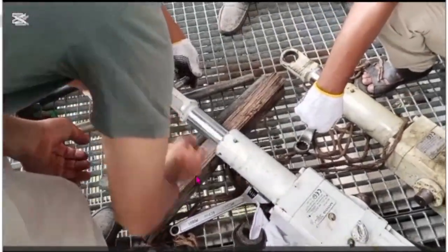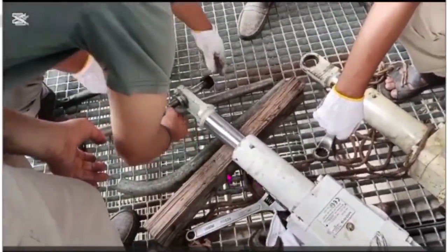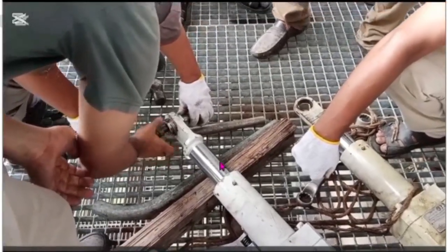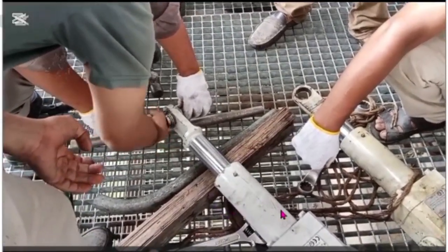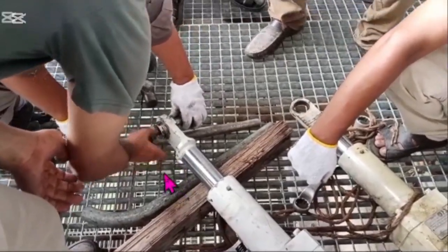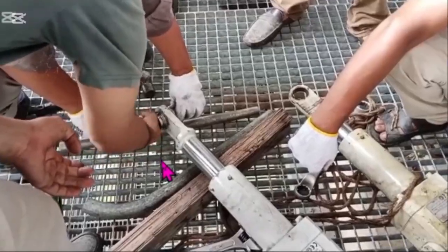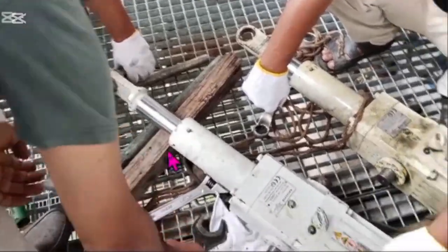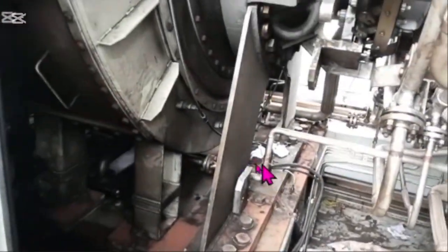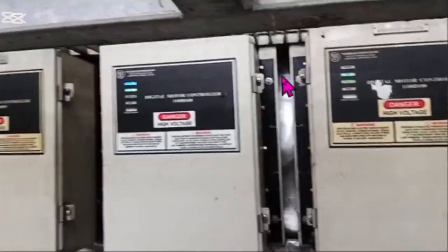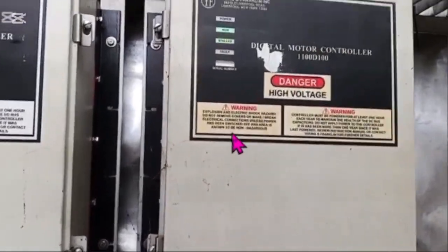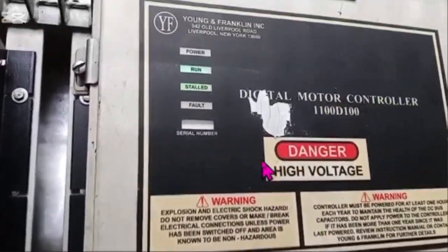Manually we checked that everything was okay. After that we connected these units to our driver position, that means inside the gas turbine unit. Here is the connection, and the nut is connected with the bolt. Then after we inserted this driver unit here, you see, this is the position and this is the Moog controller. This is the control unit of the IGV.